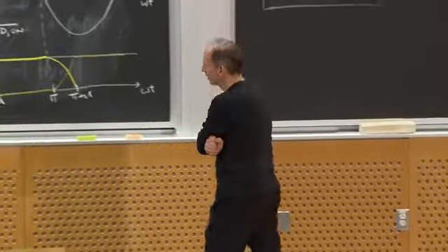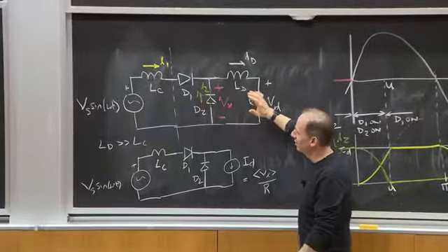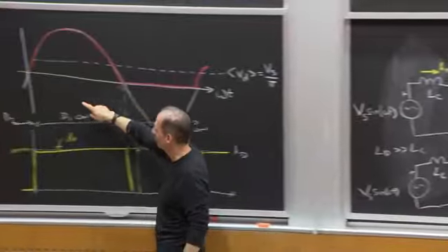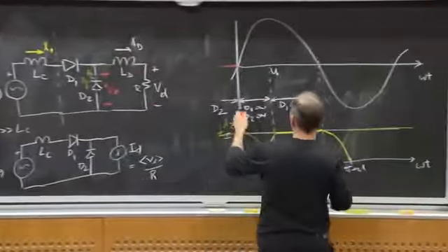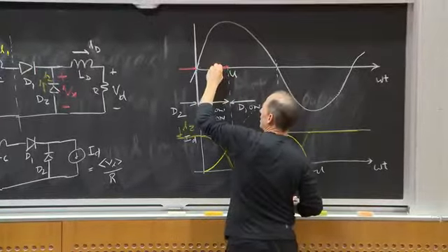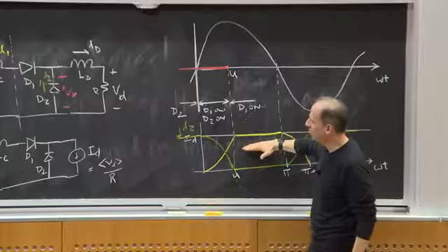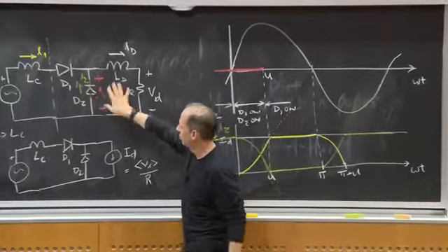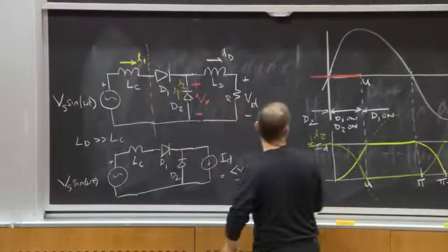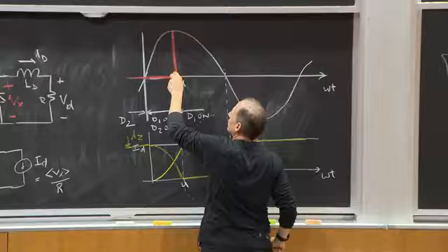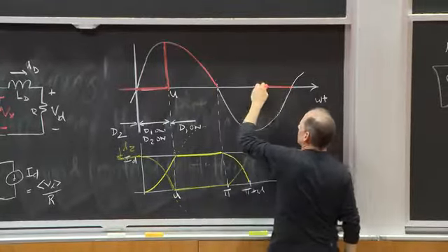Yes. Right. D2 is on. This is a short circuit. V2 better be V0. All right? So before, I got this nice sort of half sine wave bump, right? What's going to happen is, for the entire time the current's commutating, I've got 0 here. Once only D1 is on, then LC has a constant current in it, and so it has no voltage drop across it, and then I get the remainder of this. And in the second half of the cycle, it does the same thing as last time.